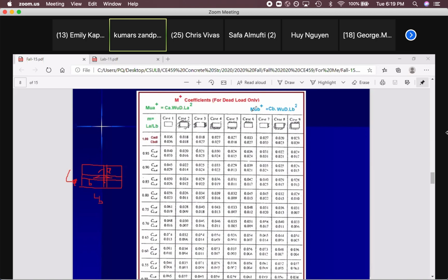So the moment that we calculate would be for 1 foot of this at the long side, 1 foot of that for the short side. So you need rebar at this direction, rebar at the other direction, because this is a two-way slab. The load will be transferred to both sides, not one direction. So you need to install rebar at both directions. How to calculate them? You have two moments, as you can see.